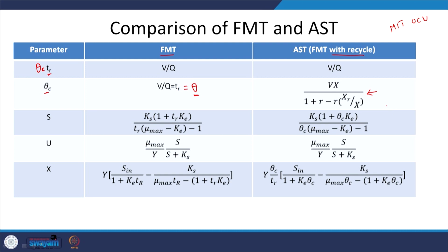For substrate, without recycle it is theta, but with recycle we have theta C, the solid retention time. HRT is typically a few hours, theta C typically a few days. So S is going to be much lesser for the fully mixed tank with recycle.